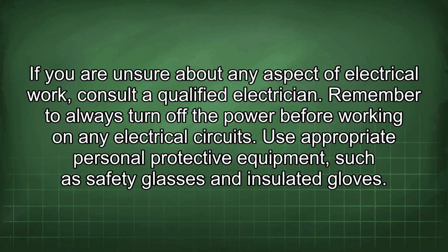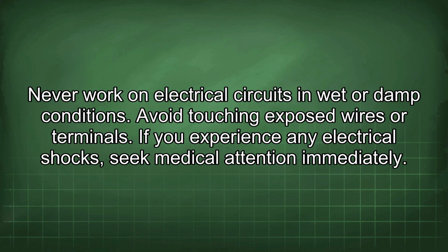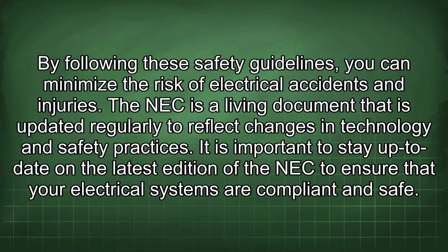Remember to always turn off the power before working on any electrical circuits. Use appropriate personal protective equipment such as safety glasses and insulated gloves. Never work on electrical circuits in wet or damp conditions. Avoid touching exposed wires or terminals. If you experience any electrical shocks, seek medical attention immediately. By following these safety guidelines, you can minimize the risk of electrical accidents and injuries.